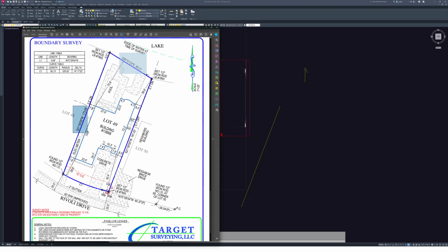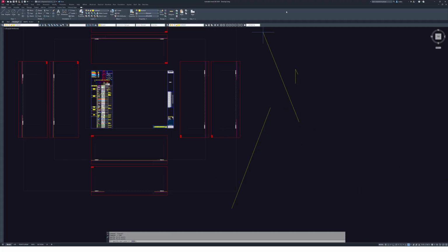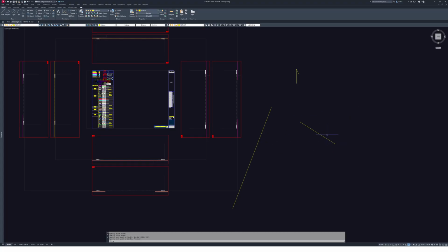So now I want to draw this line, and I'm going to draw it separately, and we're going to connect them. You can trace around, but it's usually a little bit more hassle than it's worth. So this one we want 66.21 feet, and then that's the direction. Start a line anywhere, it doesn't really matter. And we're going to say at 66.21 feet, caret south 58 degrees, 01 minutes, 33 seconds east. And enter. So now that's that line, and we can move it from here to here.